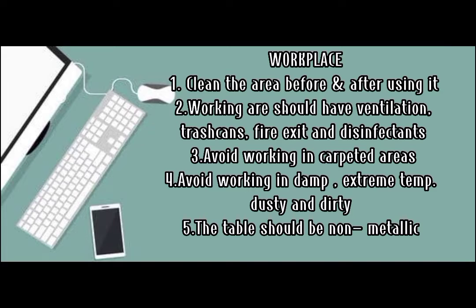When possible, try to avoid working in carpeted areas because carpeted areas greatly increase the static buildup within your body. When working on a computer, avoid places that are damp, subject to temperature extremes, dirty or dusty. And the last one is the table should be clean and non-metallic to avoid short circuits.